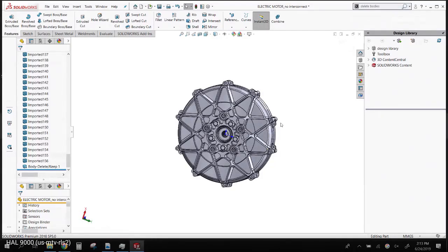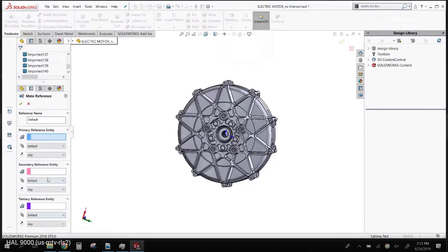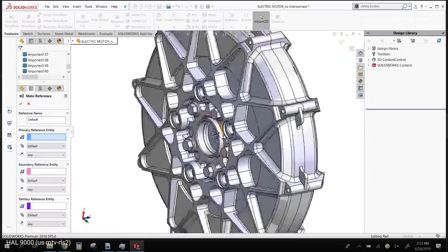I showed you mate references earlier. And it was a very simple mate reference. I didn't even name it. I just picked one edge, save, done. If you're talking about putting in nuts and bolts, that's fine. But if you're putting in something a little bit more complicated where you've got to clock it and things like that, that's why the mate references allows up to 3 different mates.